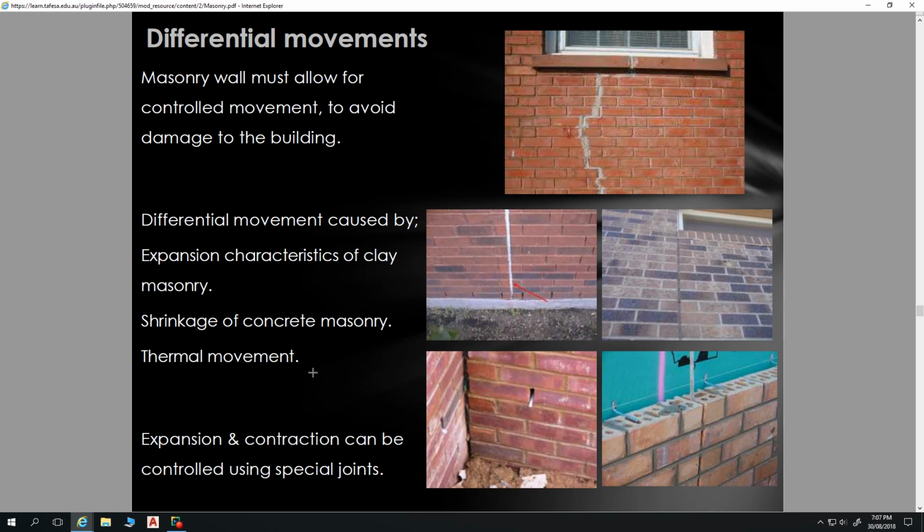Within your 10mm mortar joints, which is also your brick control joint, you use a piece of compressible foam like that. It gets compressed slightly, so that when the joint opens up slightly, that foam takes up that opening, and when it closes up, that foam can be compressed a bit. So it keeps that brick control joint fairly well sealed. And then on the outside of that, you use a mastic bead.